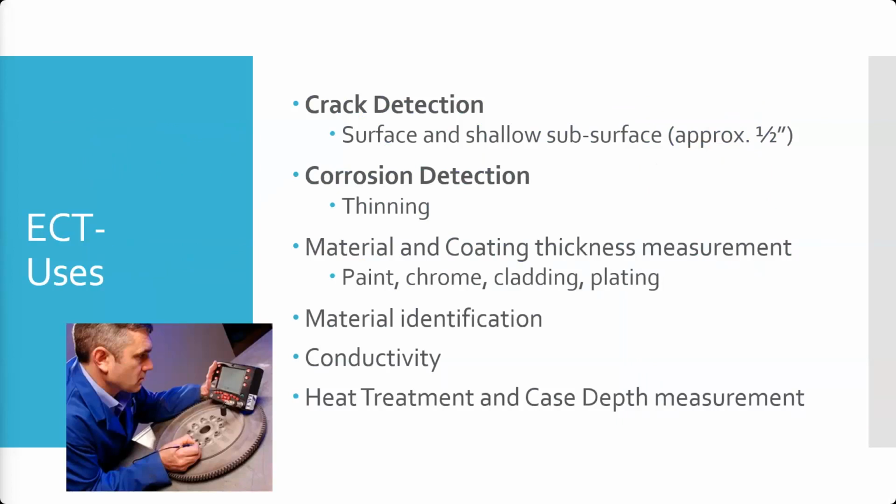especially on things like sheet metal. And where you have a lap splice, two pieces of metal, right? The corrosion tends to form between the two pieces of metal. An eddy current test is able to pick up that corrosion that might be occurring between two pieces of metal that are riveted together, or on the backside of a piece of metal where you can't access the inside of it.